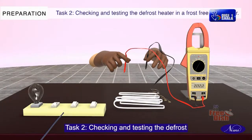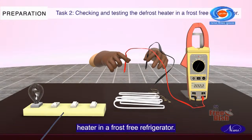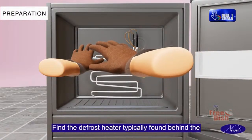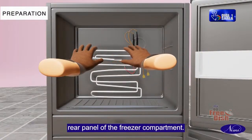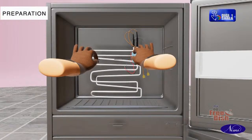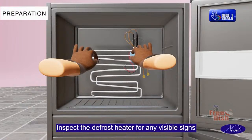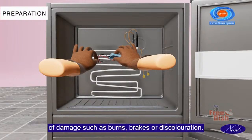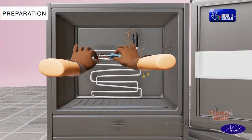Task 2. Checking and testing the defrost heater in a frost-free refrigerator. Find the defrost heater, typically found behind the rear panel of the freezer compartment. It may appear as a coiled wire or a glass tube. Inspect the defrost heater for any visible signs of damage such as burns, breaks, or discoloration.